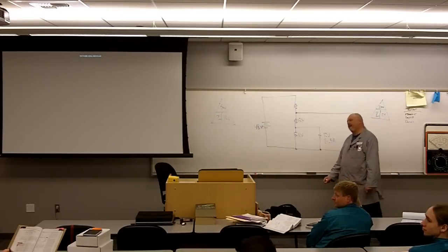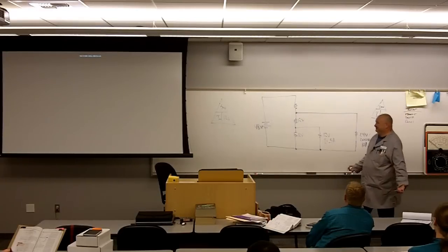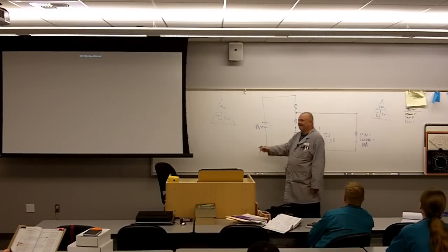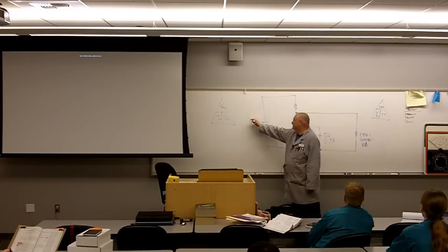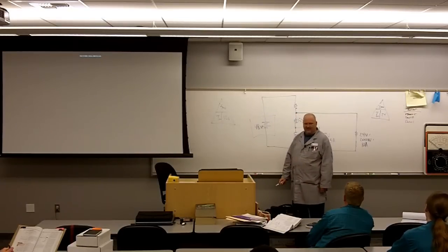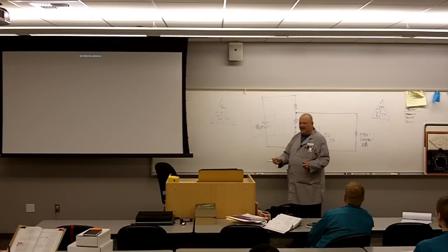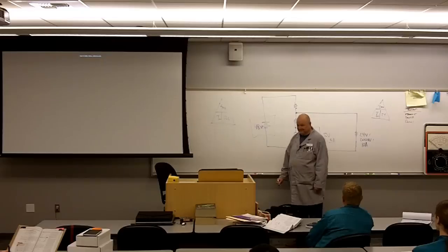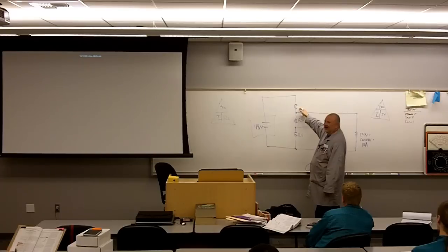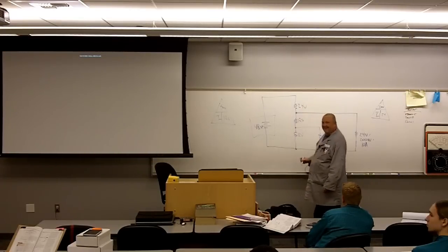Question? There's the other resistor up there that's hanging out by itself doing nothing. It's 24. It has to be 24, right, to get 48? Why wouldn't it? Remember, I bought this military surplus. This is a 48 volt power supply, okay? So it converts my ship's power to 48 volts DC. That's still 48 volts at the end of it, it's all coming back together. Yeah. So if this is 48 and this is 12 and this is 12, what's this got to be? 24. Why? Because you've got to drop it down to 24 volts.